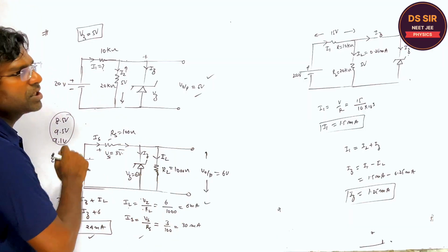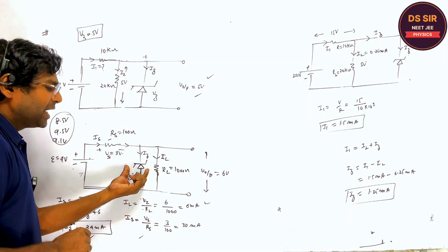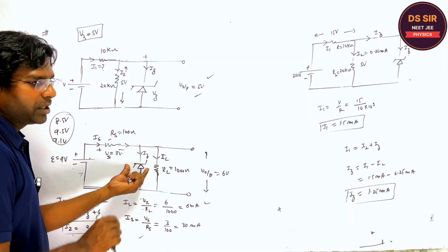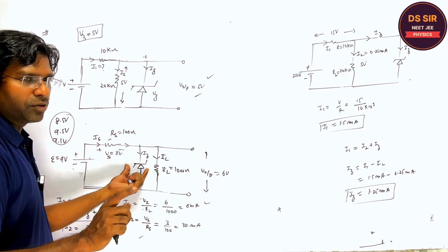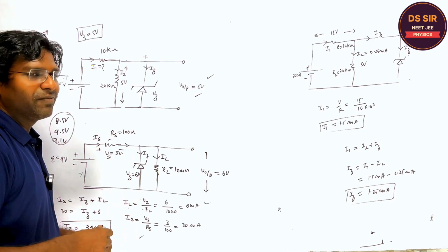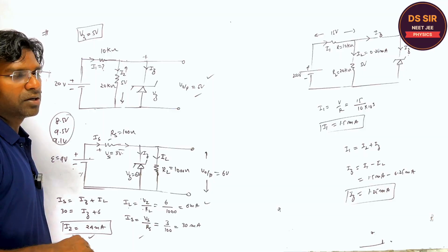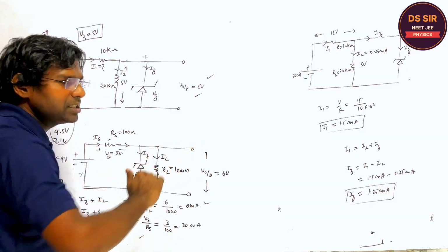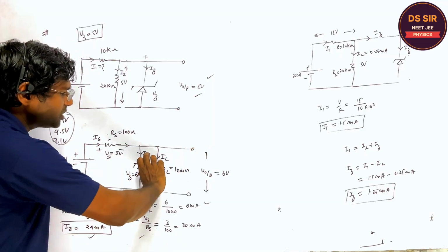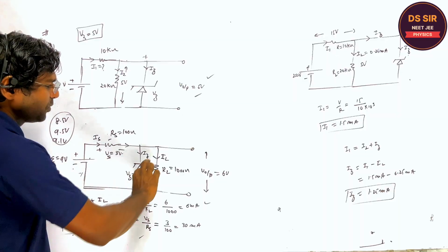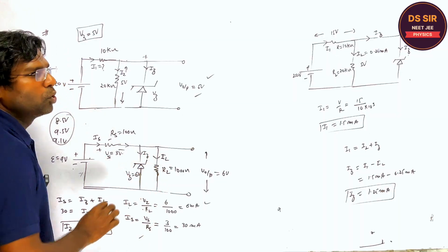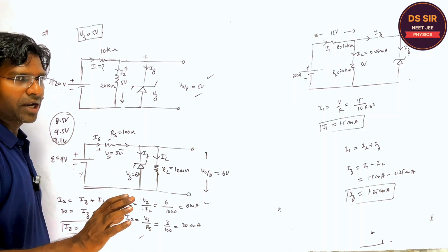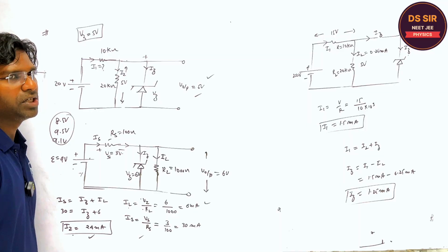So this is the application of the Zener diode, as a voltage regulator. You have to remember. Are you getting or not? In all devices like your mobile charger, where a constant DC supply is needed, this Zener diode is always connected in parallel with the load resistance like this, right? So this is the application of the Zener diode.